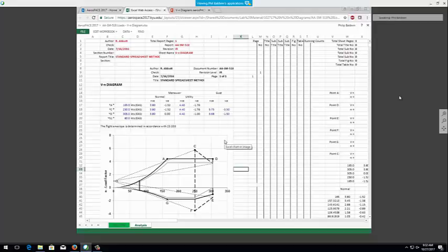It doesn't have to be, and it could be less than CL max, but it definitely couldn't be more than CL max. Aspect ratio, parasite drag, Oswald's efficiency, the propeller pitch to diameter ratio. If you have a lower pitched prop, you get more static thrust, which helps low speed, and a higher pitched prop will have more thrust at a higher speed. And then the launch velocity, which I call V-throw here.